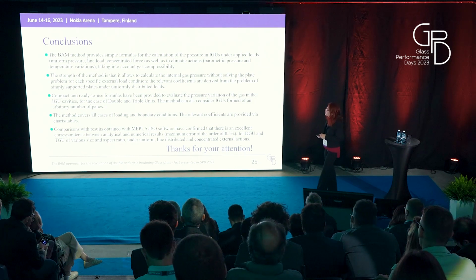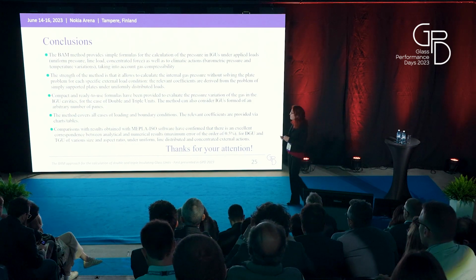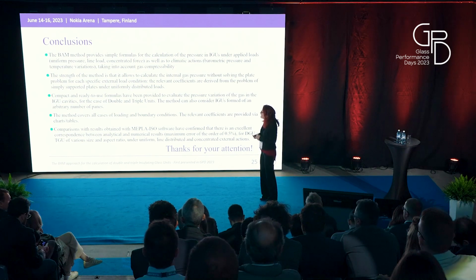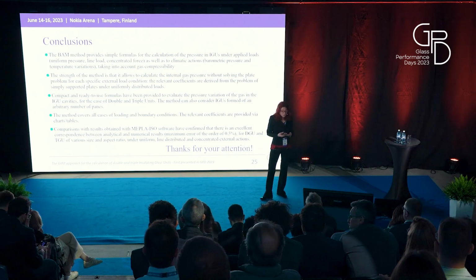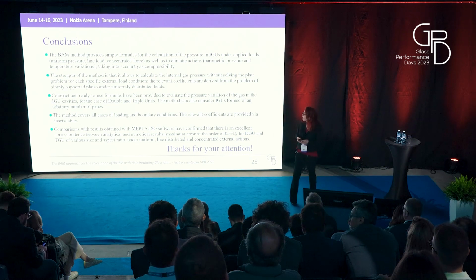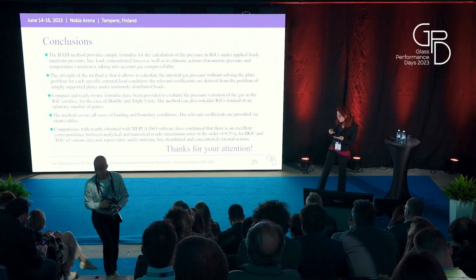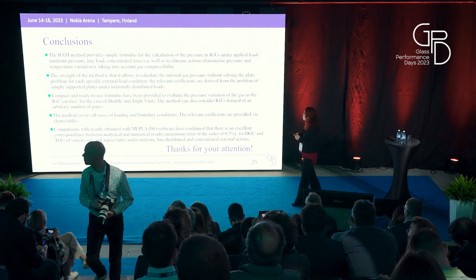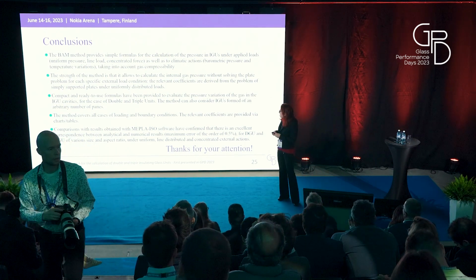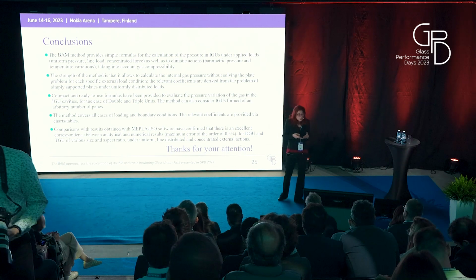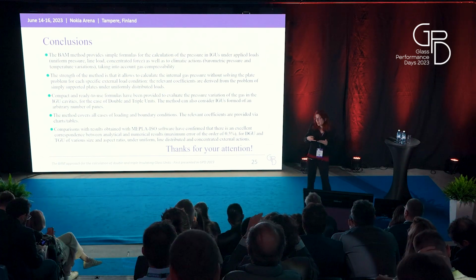So, in conclusion, this Betti's analytical method provides formulas that are very easy to implement and allow evaluating the load sharing, so the pressure change in the different cavities of IGUs. It can also be applied to the case of IGU under climatic loads.